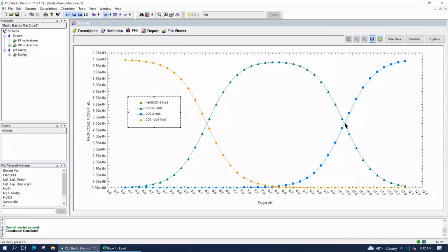And then at pH of 10.3 or thereabouts, you have bicarbonate and the carbonate again. Now here's the free carbonate ion, and you can see at about 10.3 pH, their concentrations are roughly the same. That's called the second dissociation constant at 10.3. So since carbonic acid has 2 acids to give up, you have a pKa1 acid dissociation constant, pKa2, and the value of pKa1 is 6.3 or 10 to the minus 6.3. pKa2 is about 10 to the minus 10.3.